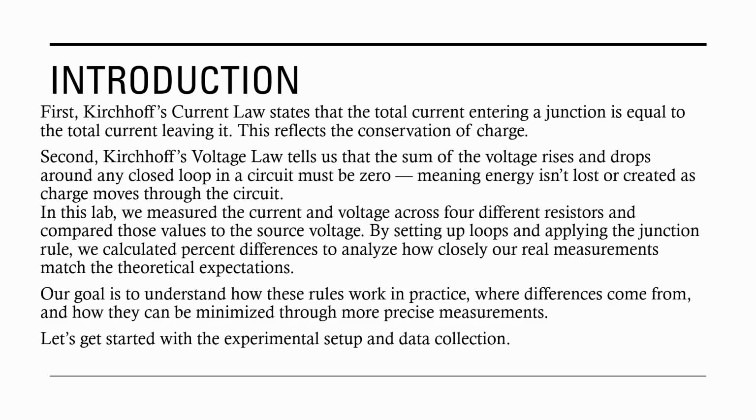Introduction. First, Kirchhoff's current law states that the total current entering a junction is equal to the total current leaving it. This reflects the conservation of charge. The second law of Kirchhoff is the voltage law. It tells us that the sum of the voltage rises and drops around any closed loop in a circuit must equal zero, meaning energy isn't lost or created as charge moves through the circuit.